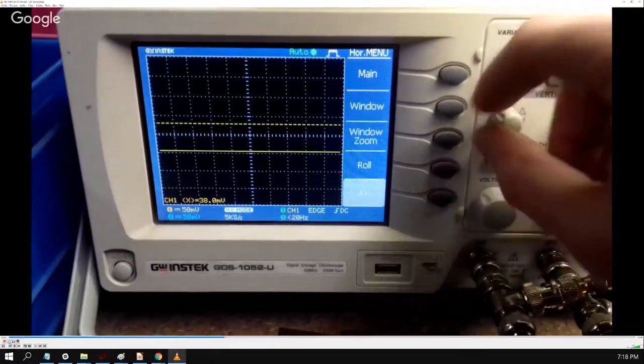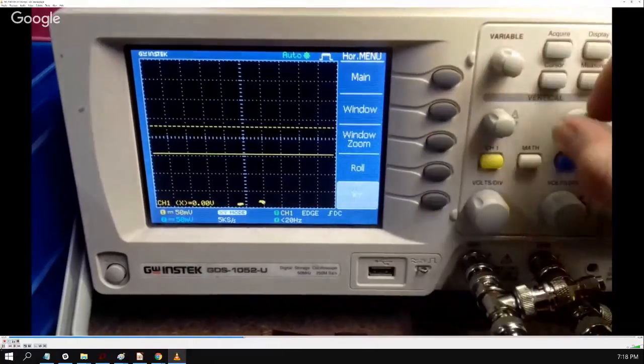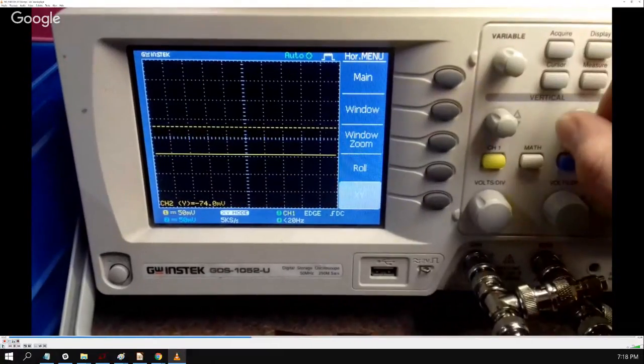All right, so I'll start from the beginning again, but I'll just give you a little explanation about what's happening here. This is observing the I and Q channels that come out of the mixers and the low-pass filters. If you recall, the I and Q are basically the XY components of the Cartesian plane.